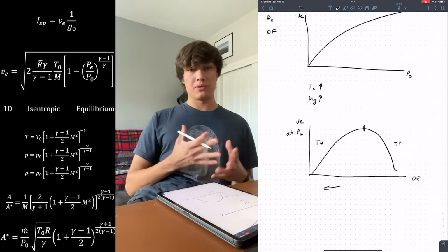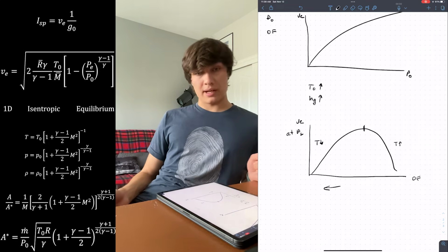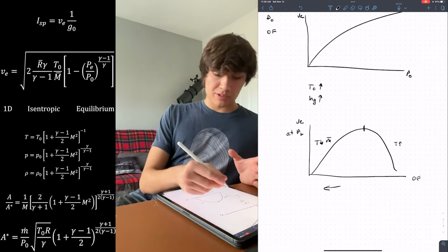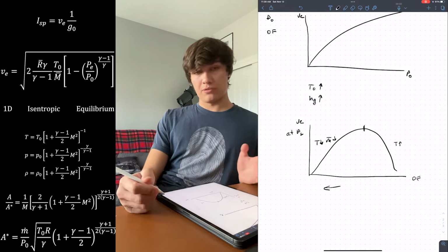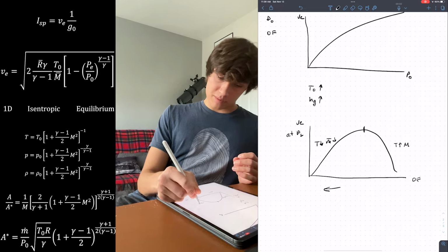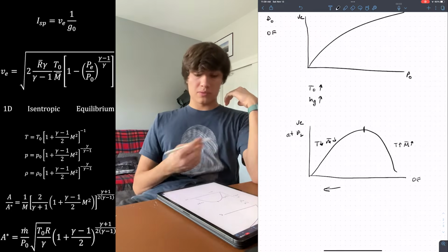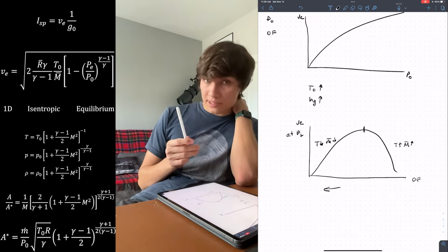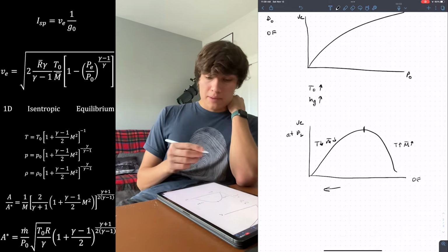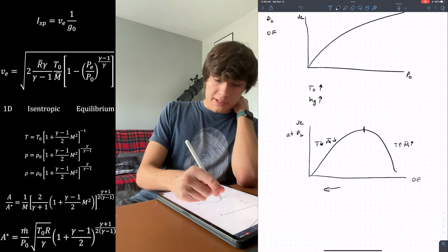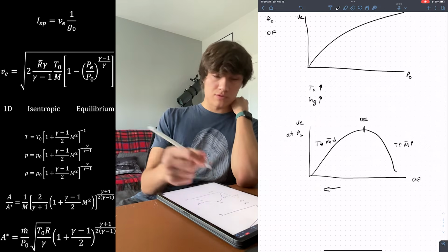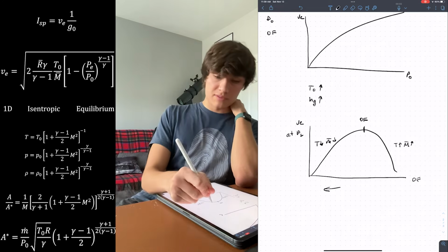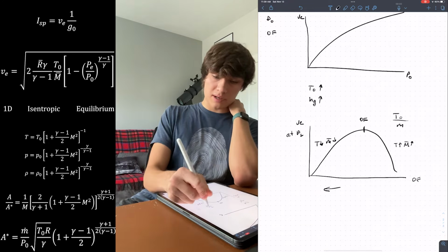This is familiar to you if you know about car engines. But the other effect that happens that isn't proportional to this is that the average molecular mass is also low on the fuel side, and it becomes high on this side as well. So if you remember, efficiency is good when you have a high temperature and a low average molecular mass. So there is some ideal OF ratio for each pressure that maximizes this effect of T naught over M bar.